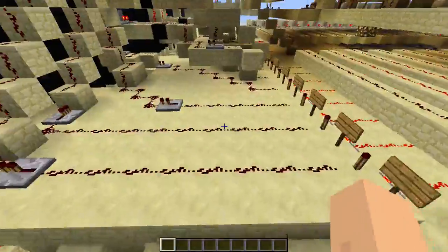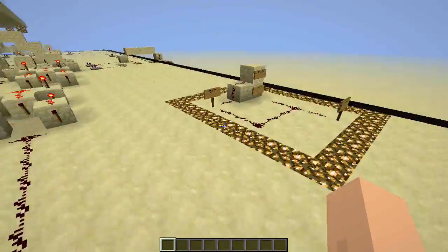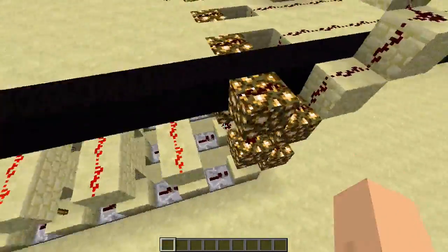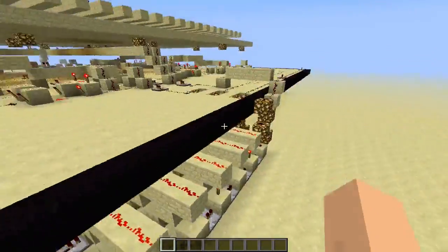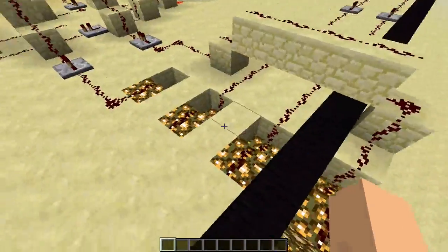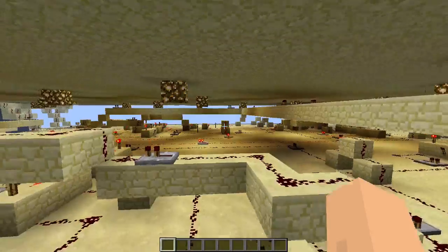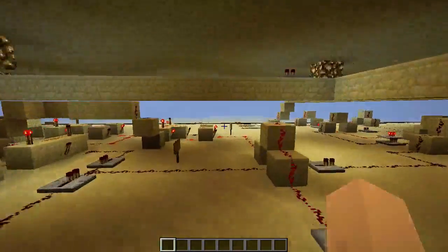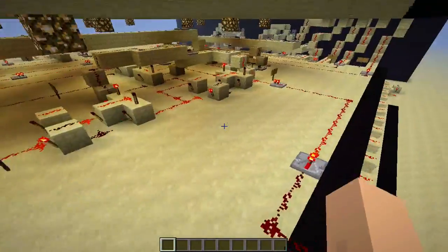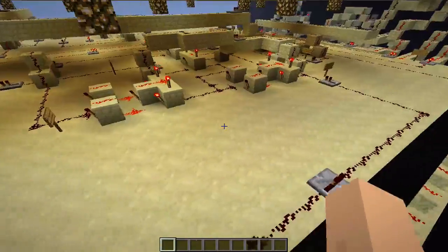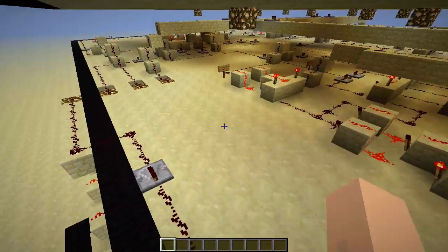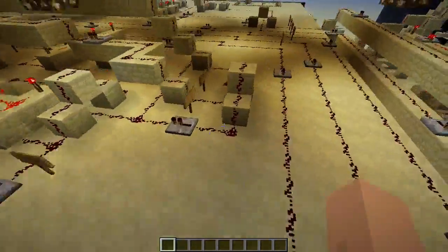So as you can see, at the second layer is where the ALU is located. We have 2 inputs. These inputs are the 4 binary digits from the buttons. So we've got the 4-bit binary number from button B, the buttons on the right, and then on the other side we have the binary inputs from buttons A, the group of buttons. So with these numbers we can calculate the added total by using a lot of full adder circuits.